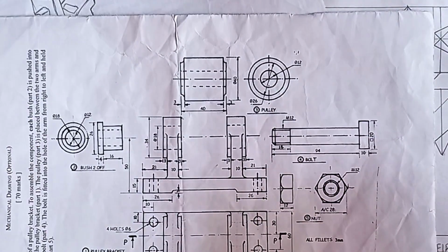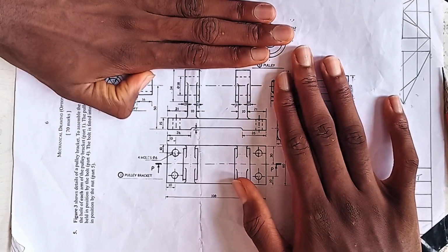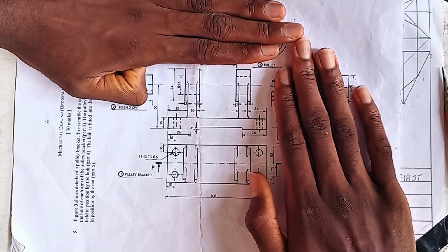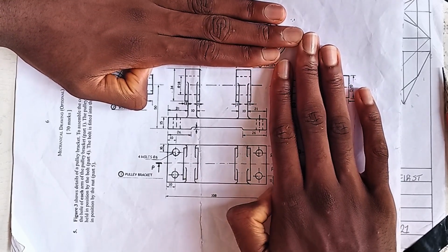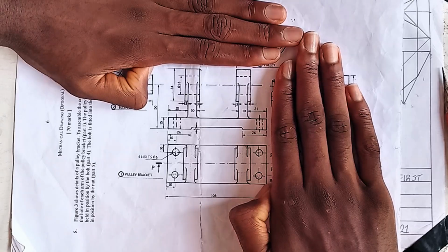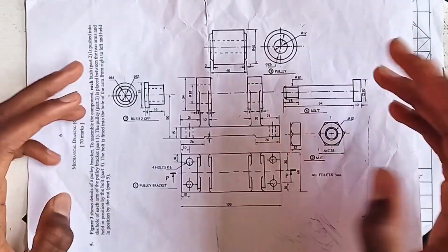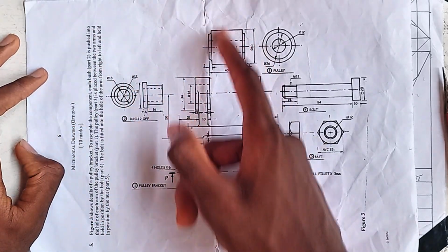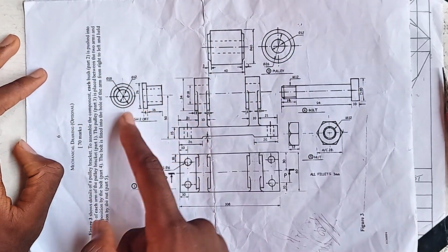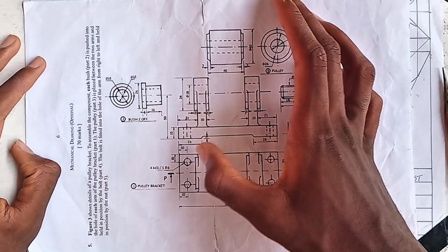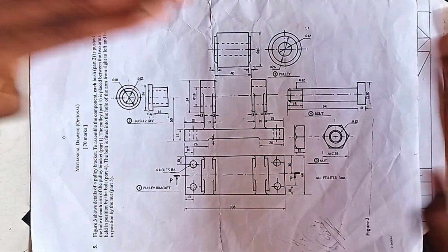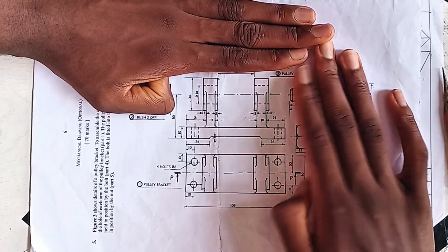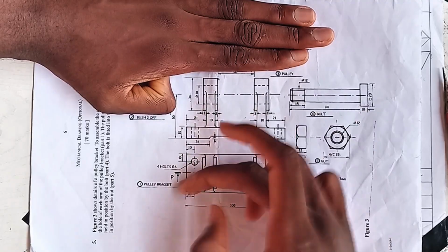So I want you to, okay, let me cover these other parts so you understand everything clearly. So I guess you're not seeing what I'm seeing. You're actually seeing two parts. Normally in first angle orthographic projection, we always see the front elevation at the top left corner, the end elevation at the top right, and the plan at the bottom left corner of the A4 paper or the drawing paper. So now, when you cover these components for now, what are you seeing? You're seeing only two parts. You're seeing these two blocks, two different parts.